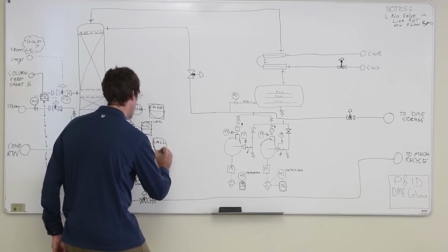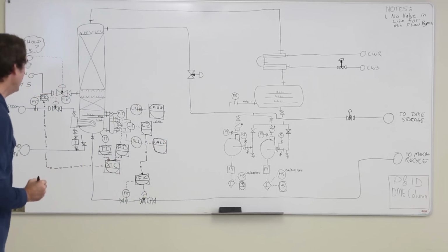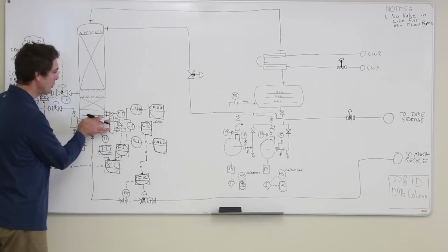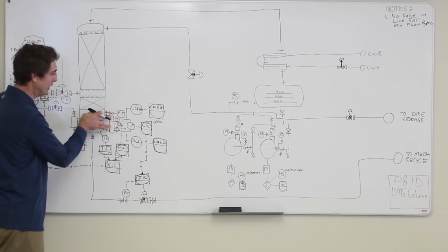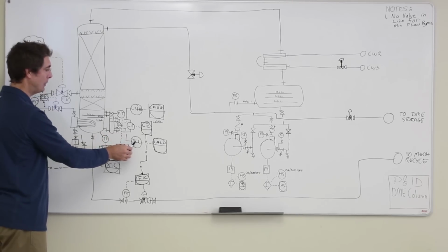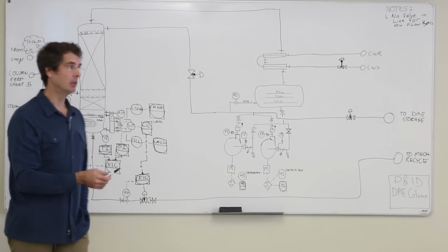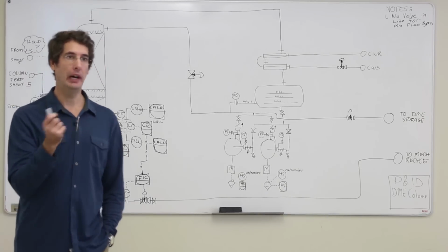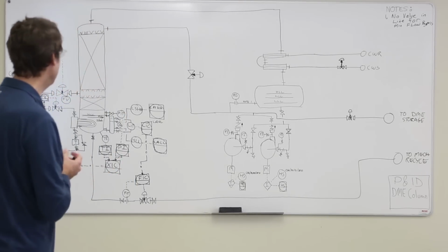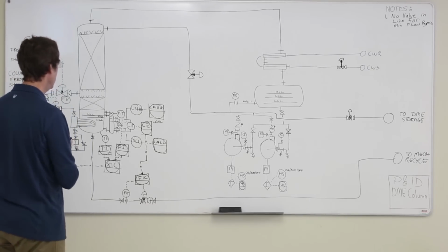You can see how these things get complicated fast, eh? And I've purposely put the level switches inside the level transmitter so that if the level switch is alarming, I still should be able to see something in the level transmitter. That's one of the learnings from one of the safety incidents that, if you look at the CSB, you will see.